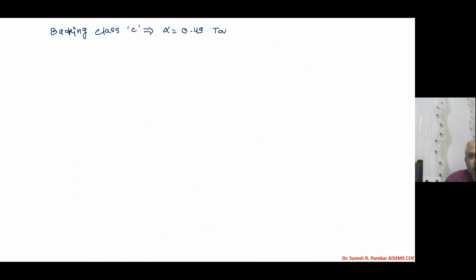We have table 7, which is imperfection factor. And therefore now by 7.1.2, page number 34, we have to first find value of phi. So phi we have 0.5 in bracket 1 plus alpha in bracket lambda E, equivalent slenderness ratio, minus 0.2 plus lambda E square.